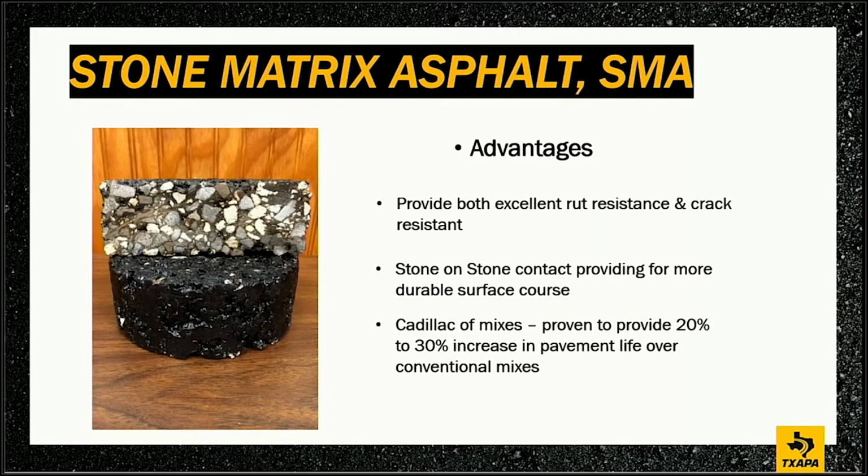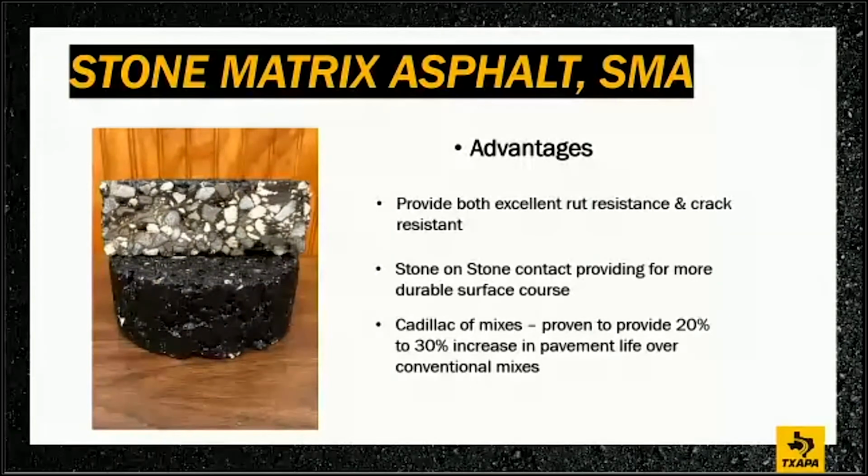It provides both excellent rut resistance and resistance to cracking. I mean, it almost looks really oily, and it does. It has a lot of oil in it. There's very little fines in it at all. It's mainly stone on stone. Okay, you can just look at that cutaway. It's stone on stone all the way through it. And then we call this the Cadillac of mixes.